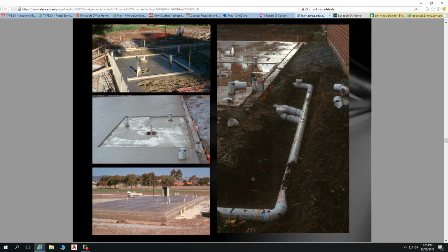In that scenario, you have overflow protection on your bath, overflow protection on your basin, etc., which is just a small little hole that, if you were to plug up your basin and turn the tap on, that water, instead of spilling out onto the floor, is going to go into overflow protection, which is going to go into the pipe for your basin or for your bath or whatever, or laundry tub.